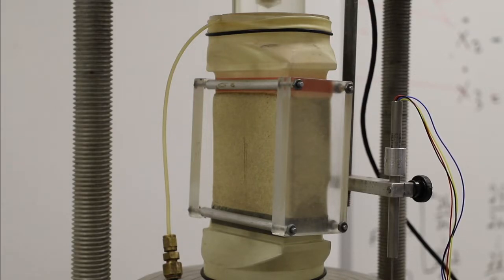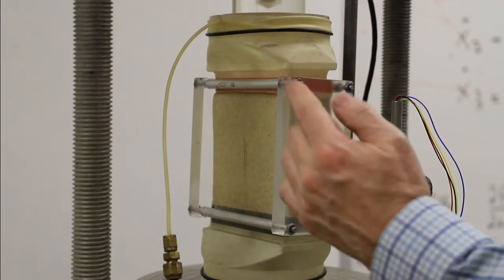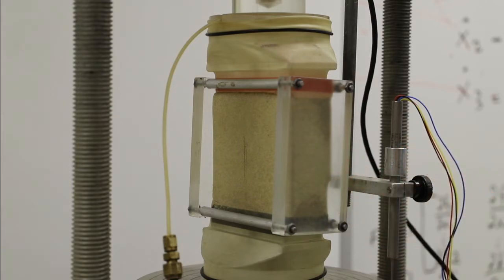Okay. So we're going to continue for just another moment or two, and then we'll take the plates off and you'll get a really good look at how that shear band occurs. It's right up at the top cap on the left and cutting down steeply to slightly above the cap over on the right side.